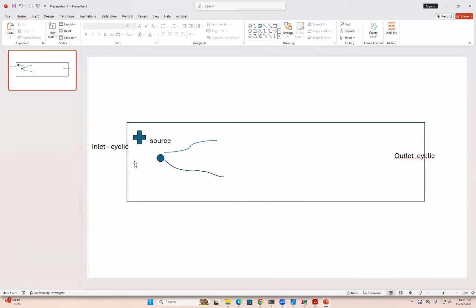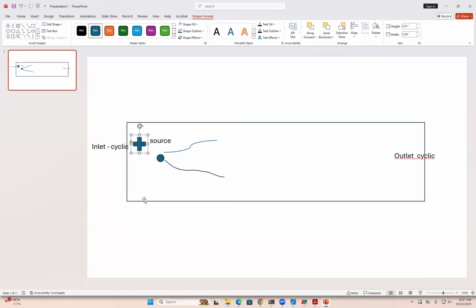Okay, then it will be a multi-phase flow, because both phases are liquid, water plus water with different properties. Both are water, so not particles. Water with different properties means that is another fluid, right? Yes, exactly, two fluids. The second fluid is basically coming from a source, because if I add another tube and other things, it becomes very difficult to create a mesh. The more you keep adding to the main geometry, the more complex the mesh becomes.